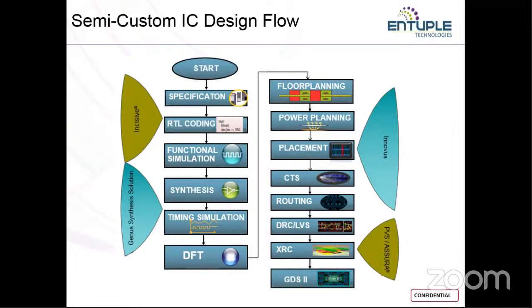So your tool has to understand what that refers to. For that you need to map your HDL with the tool, with the help of some libraries. This part of mapping the HDL with the tool is called the elaboration process, and then you simulate. You check how your RTL design responds to a particular input, so for that you work on the functional simulation.